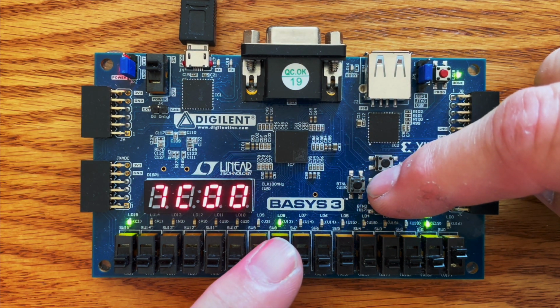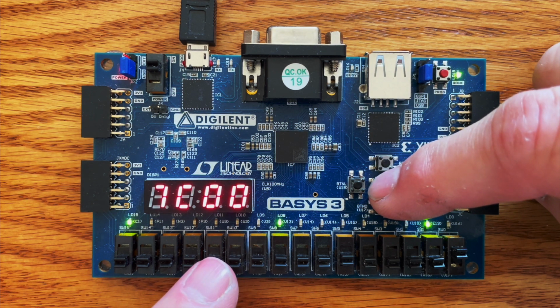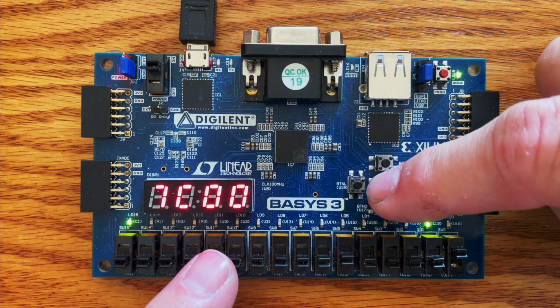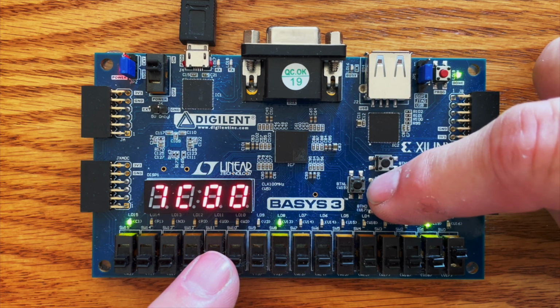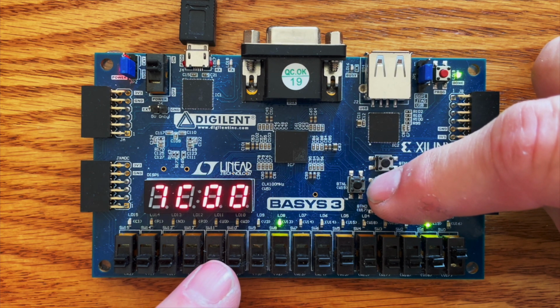When the center push button is pressed, you'll see LED 8 come on and stay on as long as the button is pressed. As when setting the dividend and divisor registers, when the center push button is pressed, you'll see LED 11 quickly flash on, then off, as the rounding mode is latched into its respective register.